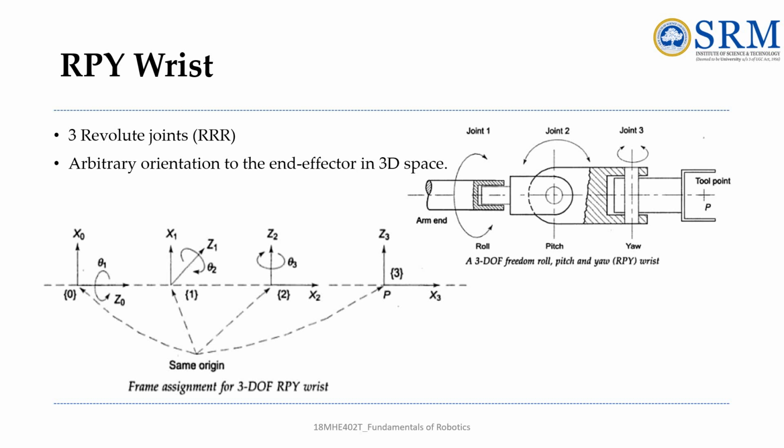So here according to the roll joint there is no link length and rotation about x-axis is here 90 degrees, that is minus pi by 2, and there is no offset, so that is also 0, and theta is there. Okay, so theta is theta 1. Then about pitch, here also there is no link length.